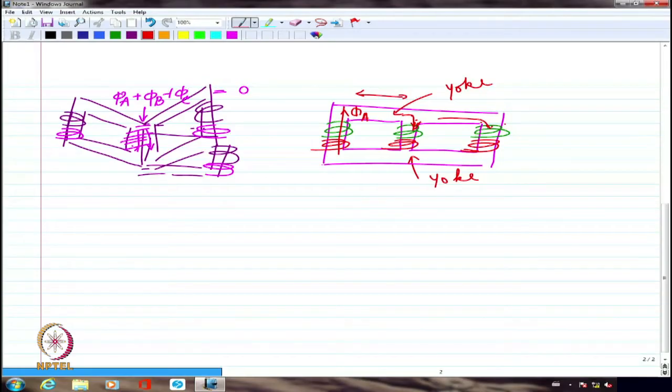Yeah. So now why do we need this yoke? Why do we need a magnetic circuit amongst these all? If you don't have magnetic circuit, where is the question of electromagnetic induction? Basically, individually, A is an auto transformer, B is an auto transformer, C is an auto transformer, and we're linking all of these through wires. But the magnetic lines that are actually coming up because of the current flowing have to find a closed path. How will they find a closed path? If you don't provide any other path, then what will happen is it will go through the air.